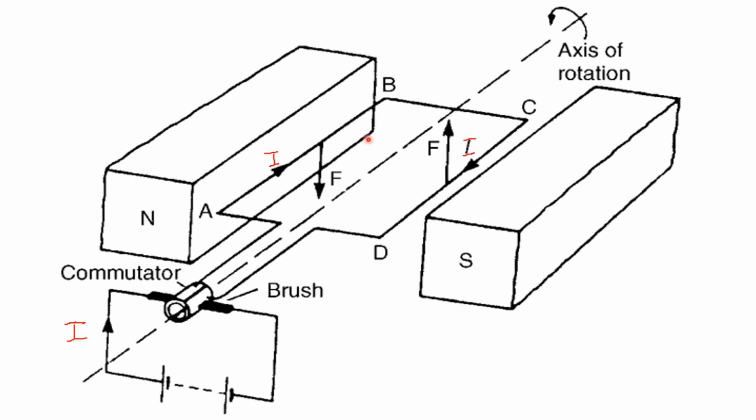It's important to note that as this current flows through the loop, there is some amount of flux change that tends to induce an EMF in this coil as it keeps cutting across the coil. Remember that if a coil is placed in a magnetic field and a galvanometer connected across the coil, then some amount of current will be recorded. This is because magnetic fields tend to induce some amount of EMF and hence current in a coil placed in that magnetic field. We call it the back EMF, since it is produced such that it opposes the original EMF or the change producing it.